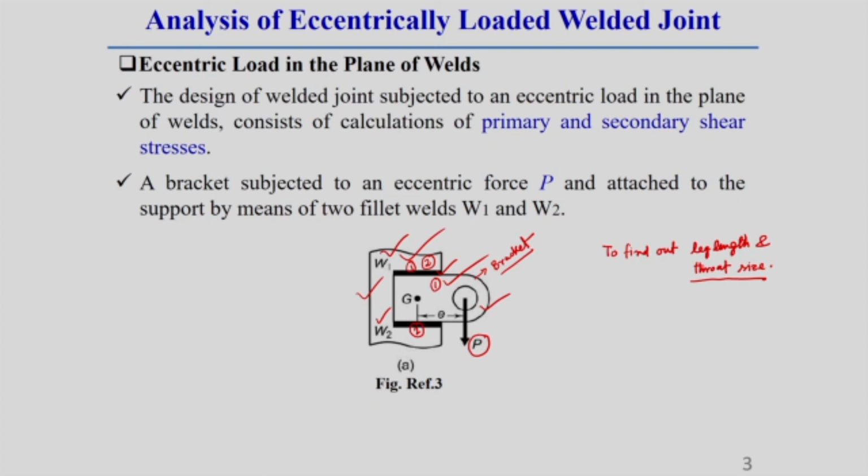So, this is our design consideration here. To find out these things, I will discuss the detailed steps in this lecture. To find out the leg length or throat thickness, we have to follow some standard steps. The first step is to find out the CG of the weld.